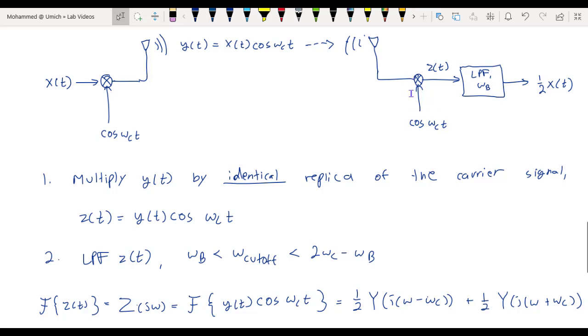However, this double sideband demodulation technique requires that the carrier frequency of the receiver demodulator is identical with that of the transmitter's modulator, and the two sinusoids are phase coherent, which means that they both have the same phase. And this is why the type of double sideband demodulator that we've just looked at is known as a synchronous or a coherent demodulator.